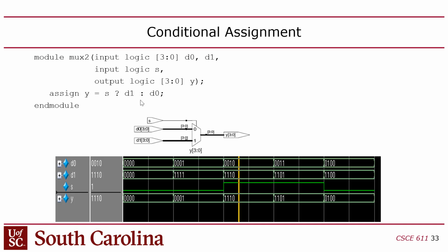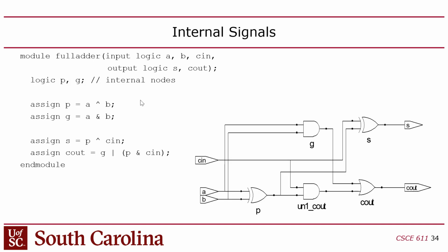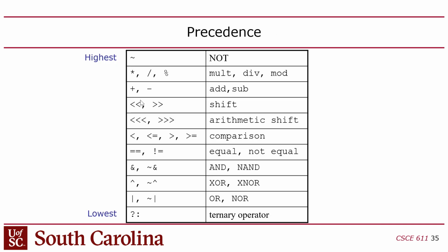And then this is a mux, basically just an assign statement with a ternary operator in there. There's another example of a full adder. Then I talked about operators in SystemVerilog. I mentioned that this table is incomplete because there's triple equals and bang double equals, the two different ways to test for equality, depending on whether you're using them in code that's intended to be deployed in a design and synthesized, versus code that's in a test bench.